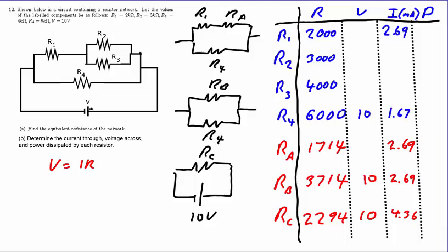We notice that on both the RA and the R1 lines, we have 2 out of the 3 V equals IR, and so we're able to calculate the third, which is the voltage. Our results of 4.61 and 5.38 do indeed add up to 10 as the total voltage, and so our checksum continues to work. We're down to one final step of disassembly, and that is we will disassemble resistor RA into R2 and R3.